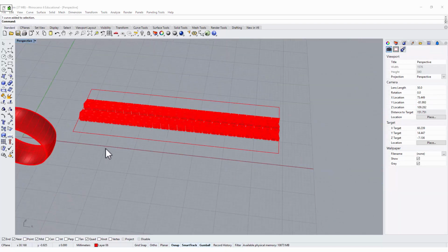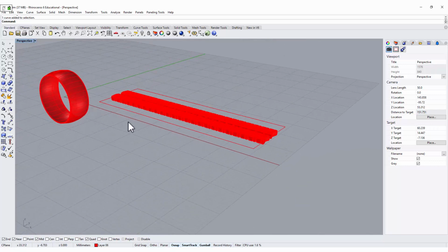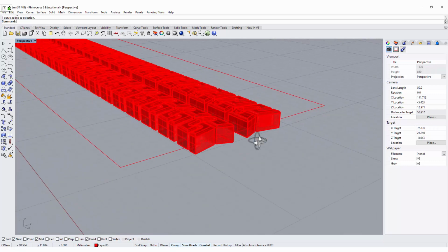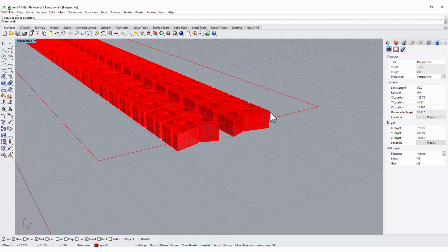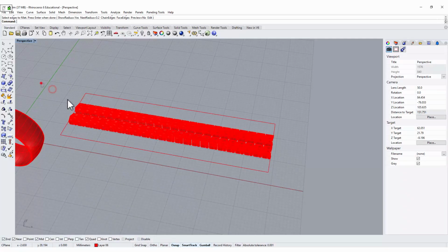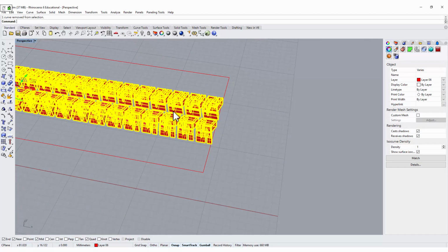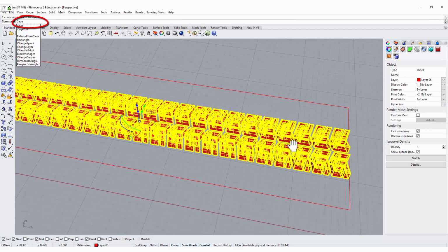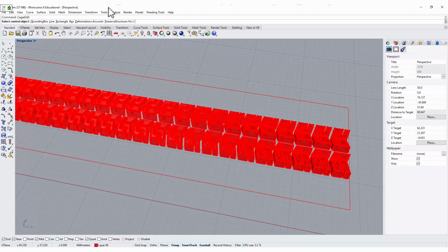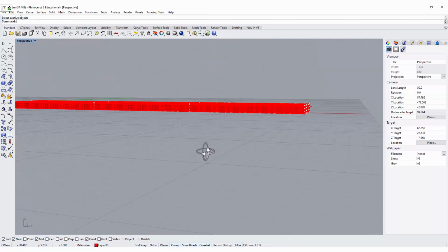Before you flow it back to the surface, one thing we want to do is make the edge smooth. Right now it kind of sticks out and it won't be comfortable for the ring. So you select everything here, not the curve there, and we're going to use the command called cage edit. We want to pick the bounding box and hit enter. The XYZ point count at this point is 4. What we need is actually Y, so we don't have to change anything here. And then very quickly, you are going to see something like this.